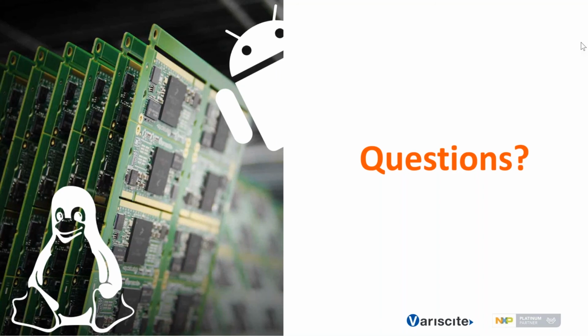We are using Laird Sterling LWB for the single band or LWB5 for the dual band. Both of them are certified for FCC, CE, and even some of the Asian countries. We copied the exact design done by Laird, so the system on module itself is practically certified as well by the modular certification.